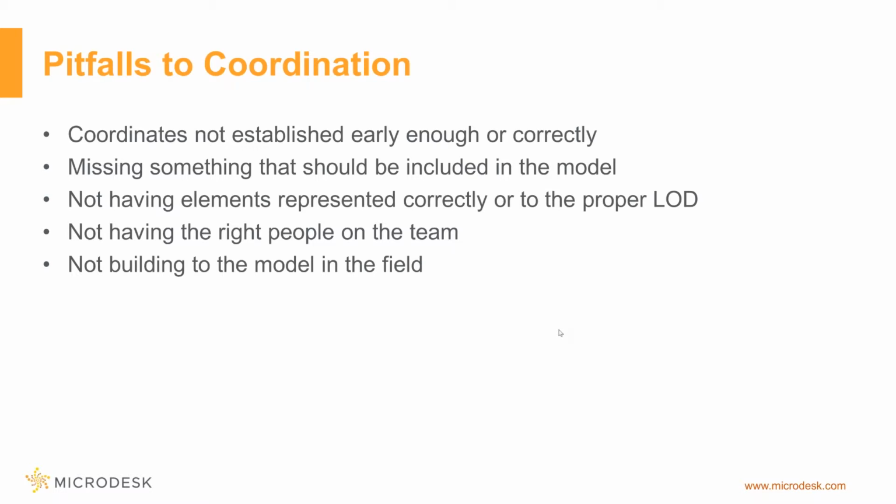Level of detail is another that we see. I talked about the valves earlier. Another example would be bundles of conduit. We talked about in this example, we said every conduit over 1.5 inches should be modeled. Well, what if we have a bundle of 24 1-inch conduits? We've seen it before where somebody says, well, I don't have to model that. It's less than 1 inch. But in reality, that bundle of conduits is a very substantial piece of the building, and something that we have to incorporate in one way or another into the model. So understanding how they work is important.